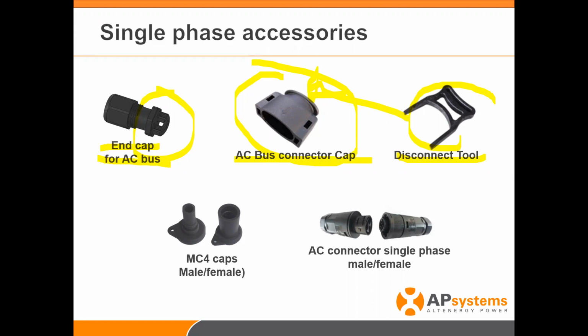One question we do get asked quite a bit, you have a dual and you have a quad. What happens if I have an odd number of modules on my roof? The simple answer is you would just cap off one of the ports on either one of the QS1 or the 600. And by doing that, you'd use these called MC4 caps, MC4 male and female. So you're basically going to cap off the plus and minus, again, watertight, dust tight.